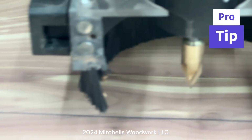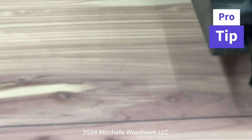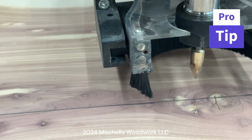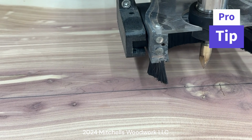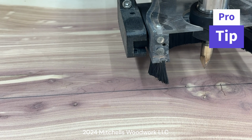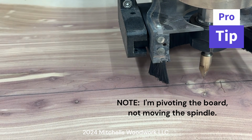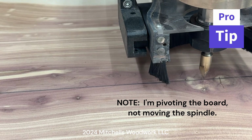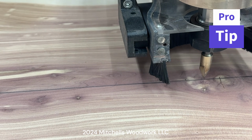See, it's already running off of that line quite a bit because it's not square to the gantry there. So let's see how much we're off. All right, so all I got to do is pivot my spindle to right there to where that's underneath that line, which it is, and put a screw in.